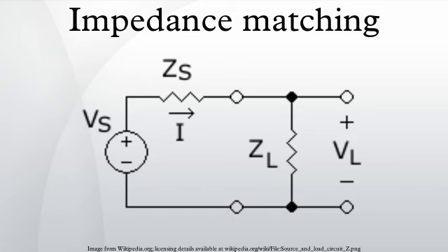Electrical examples: telephone systems. Telephone systems also use matched impedances to minimize echo on long-distance lines. This is related to transmission line theory. Matching also enables the telephone hybrid coil to operate correctly. As the signals are sent and received on the same two-wire circuit to the central office, cancellation is necessary at the telephone earpiece so excessive side tone is not heard.